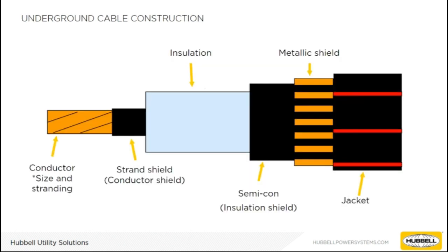Cable accessories are size-sensitive products in the way that their interfaces fit together and the way they fit onto cable. When sizing our elbows, we need to know about the conductor type as well as the insulation and metallic shield type. The conductor center is either made of copper or aluminum. This is where the cable carries current. Conductor type can be stranded, compressed, compact, or solid. The insulation insulates the conductor from ground and other conductors.